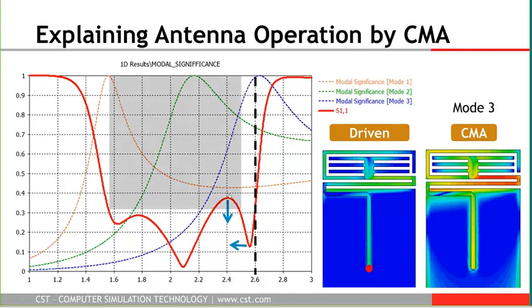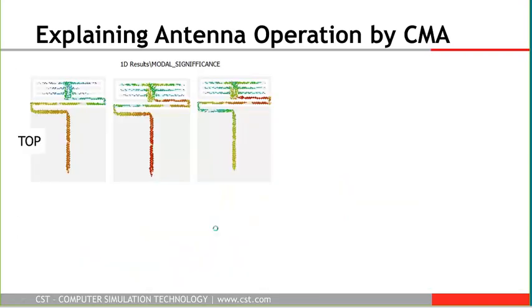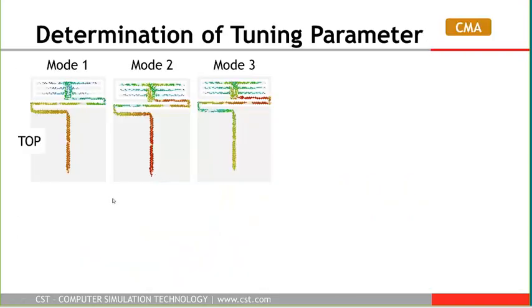So now we would like to move, so actually to fulfill the requirements, which is the gray box. The idea is to shift this third resonance closer to the second resonance, and therefore we will move this high peak at 2.4 gigahertz lower. And to do that, we need to find a way to tune mode 3 independently of the two other modes. And how to do that?